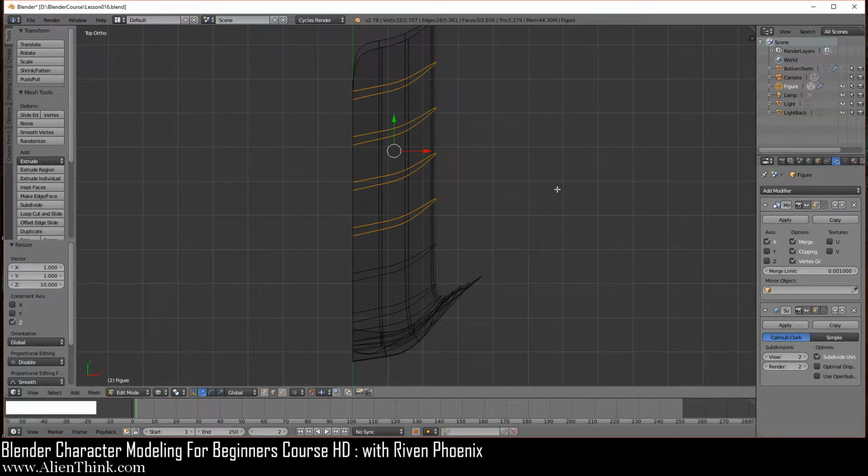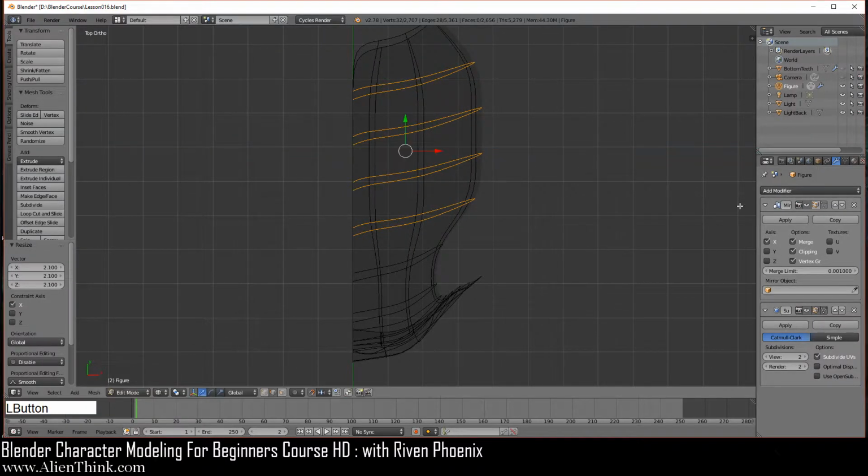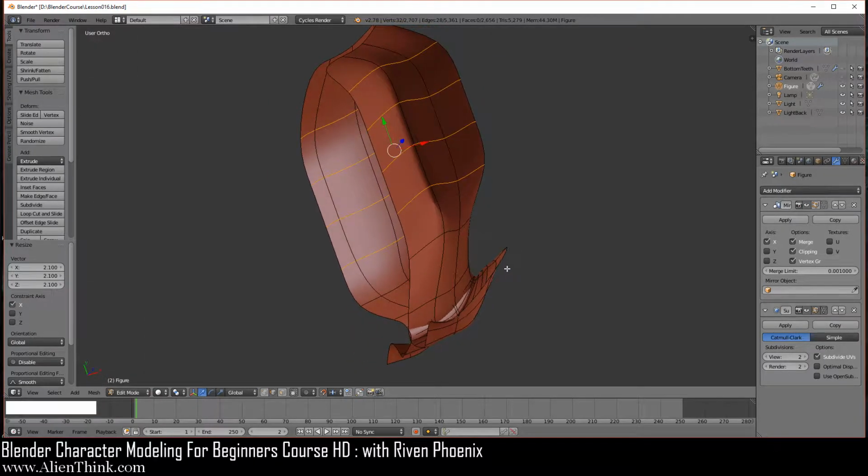Okay, now we're going to press the S key to scale, and then X on the X axis. I'm going to do 11 nudges, so it's going to be 1, 2, 3, 4, 5, 6, 7, 8, 9, 10, 11. Okay, now if you hovered your mouse over here or over here and you went over here, it will simply just jump across the screen and come over here. Okay, press the Z key and now rotate it this way over here.